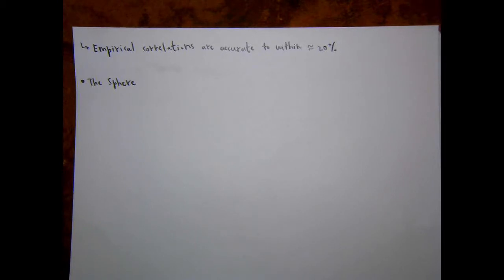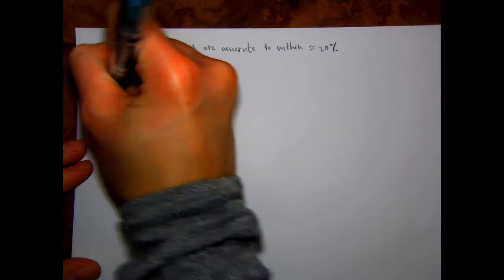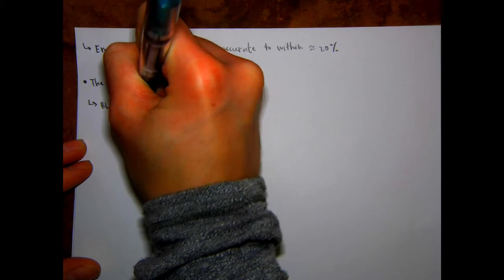And of course, for a sphere, the direction of flow doesn't really affect what the dynamics are because it's going to be symmetric no matter which direction the flow is coming from. Whereas for a cylinder, if the flow is moving across the axis versus along the axis, changes whether you're talking about something with a wake forming versus something that just looks like fluid over a flat plate, essentially. So we'll say boundary layer dynamics are similar to a cylinder in crossflow.